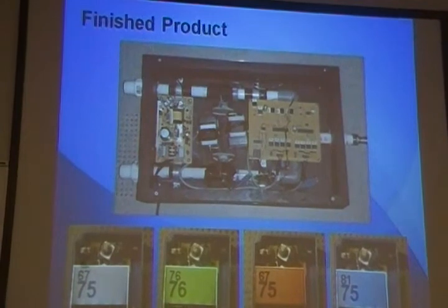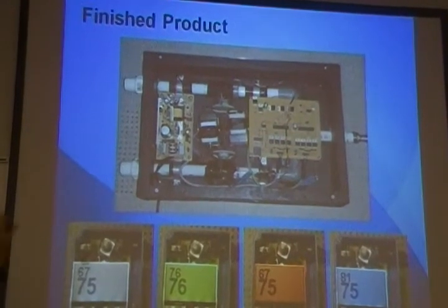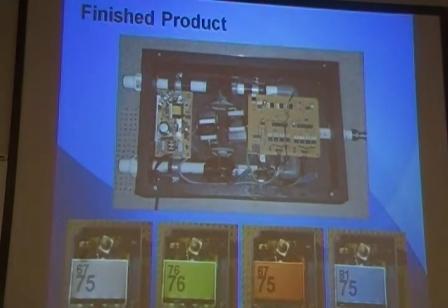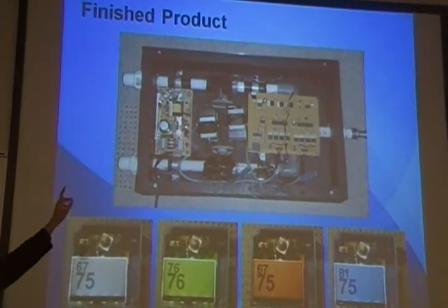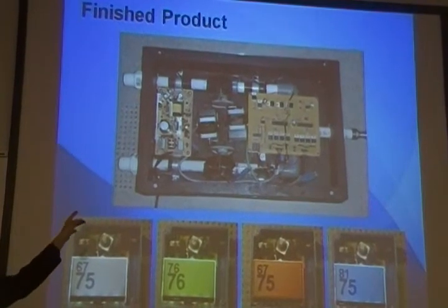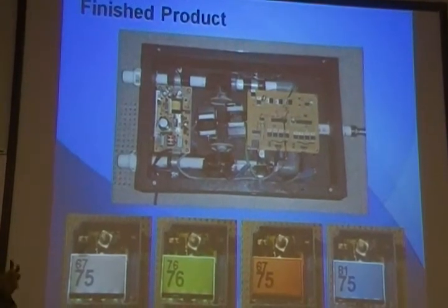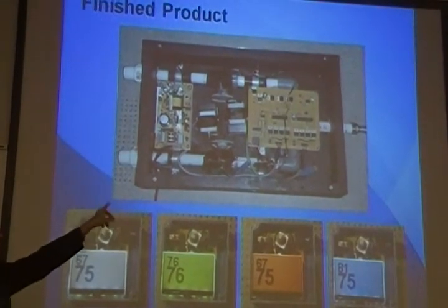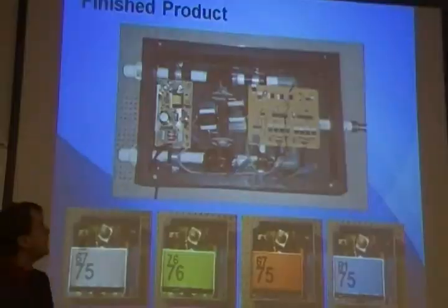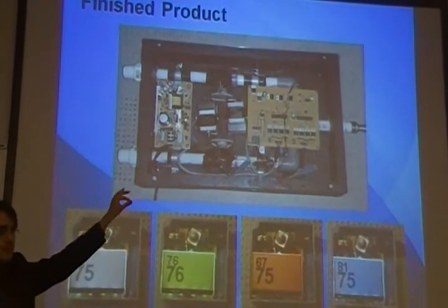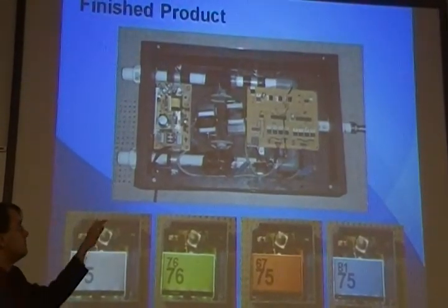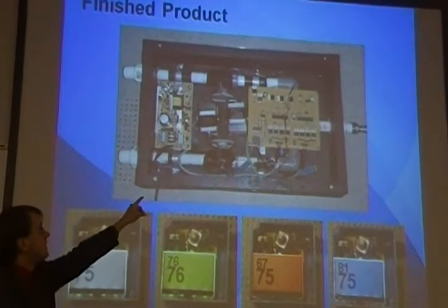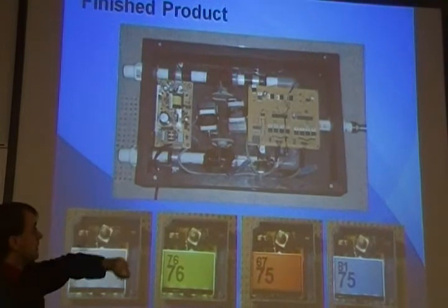And here's a picture of what we have here. You see up top there is our whole temperature control module, and down here is the different stages of our user interface. Starting up here, on the left, it looks kind of impressive, but we bought that in a store. It's the power supply for the whole system, 15 volts, and supplies over to our main board over here. It goes through 5-volt regulators, which power all the circuitry except for the motors.